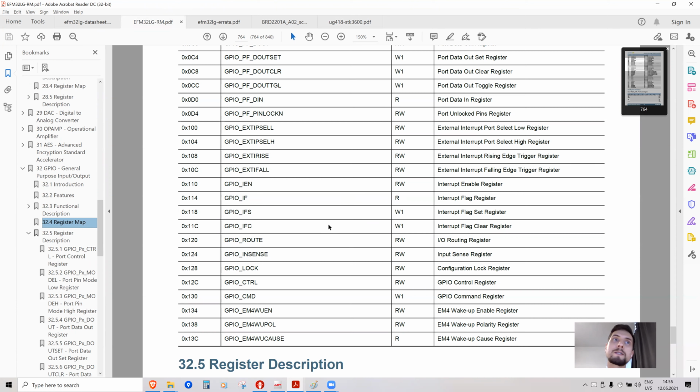So you always need to check out the microcontroller's limitations for pin interrupts. I have also seen microcontrollers that only have interrupts on 2 pins, and that's all. You cannot set any other pin as interrupt. So be careful about that. So in this case, we can have up to 16 pins as separate interrupts. They will be grouped between odd and even pins. Just don't use 2 ports with the same pin number.